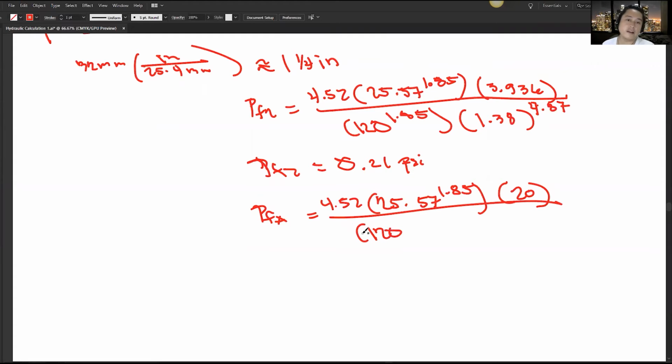That's the reason why, guys: one of our assumptions is that all the pipes in our sprinkler system are galvanized. Of course that would change if you're designing it with another material or different schedules, but as of now we're using the same material for the entire sprinkler system.